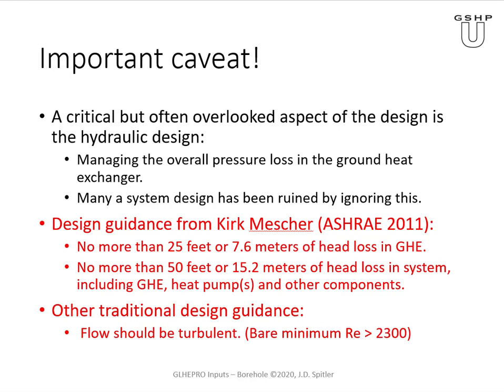I mean, if you put a big enough pump in, yes, the system will work, but there are systems where 30 or 40% of the energy goes to circulating fluid around, and that's just really a bad idea. We'll just say our own analysis shows you can often get under 10% of the total power due to the circulating pump. In other words, 90% plus is used by the heat pump.